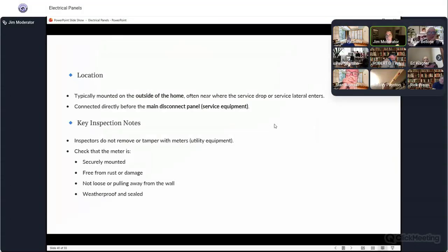A lot of times what you'll see is just some minor rust and stuff like that. You still call it out. If you see painting's been done or siding's been put on, sometimes you'll see those meters just flopping in the wind. And also, on the service drop, you'll see plastic. If they're doing gutter work or painting, Eversource will come out and wrap that in plastic for safety. You have to call them to come back and remove it. They just don't automatically know. A lot of times I'll do inspections, I'll see the plastic there, and it's been there for 6 months, and no one's removing it.